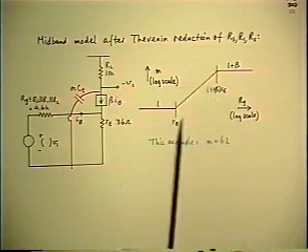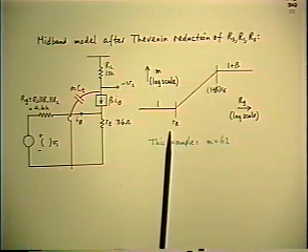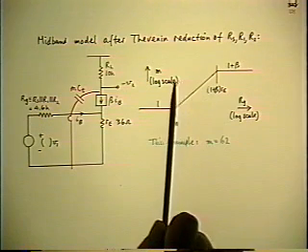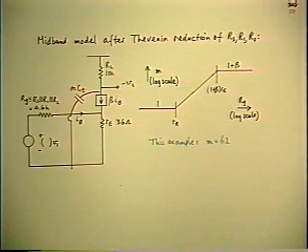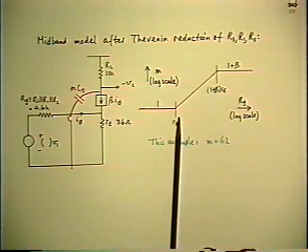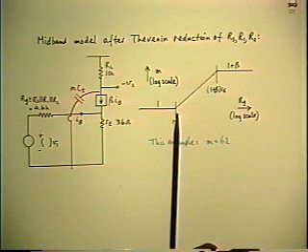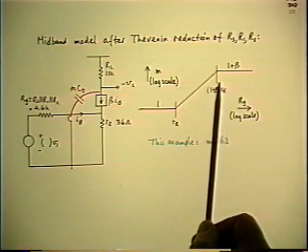But notice you get another important piece of information out of this. You get corner resistances, just like corner frequencies. And here are the values. The lower corner resistance is Re. The higher one is (1 plus beta) Re.